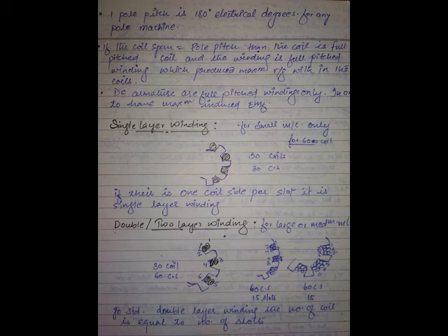Let us say each conductor here, this thin conductor, can withstand 1 ampere only. More than that, if it flows, automatically temperature rise comes and the wire will melt away. So the maximum rating is 1 ampere. Similarly, in this part also, how many amperes can it bear? Only 1 ampere. If you have two parallel paths in the armature, how parallel paths are forming we'll discuss, and if each path can bear 1 ampere, how much current rating will this winding have?